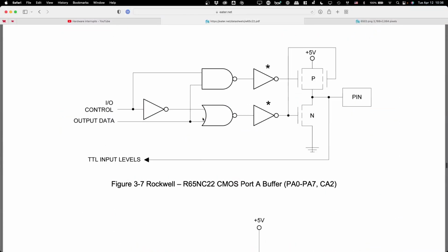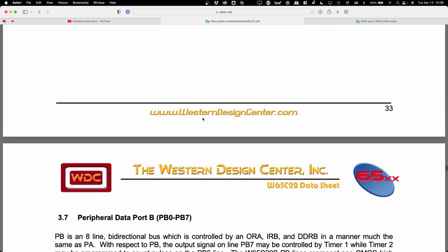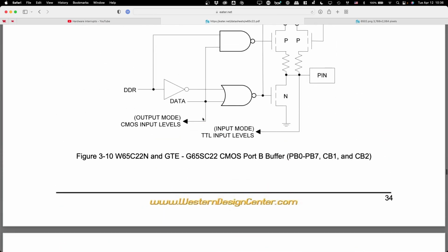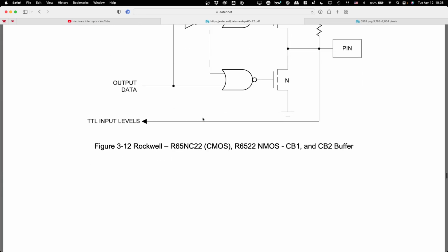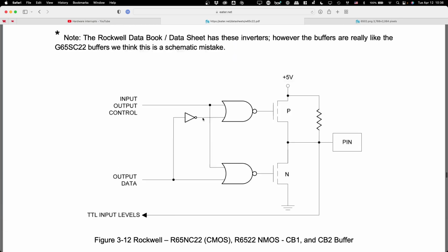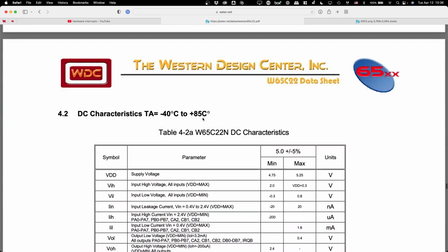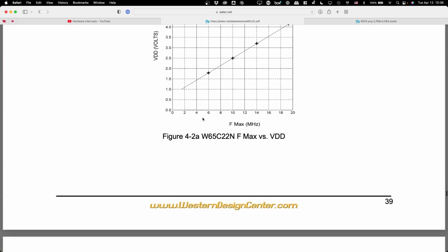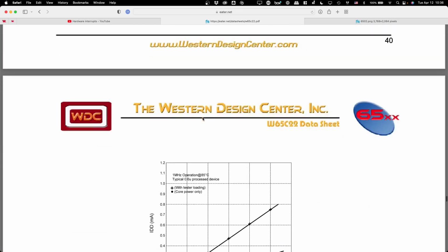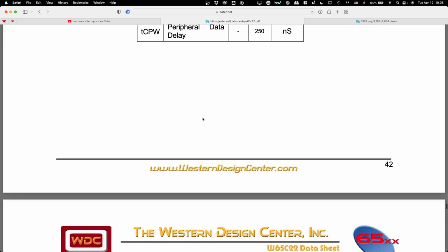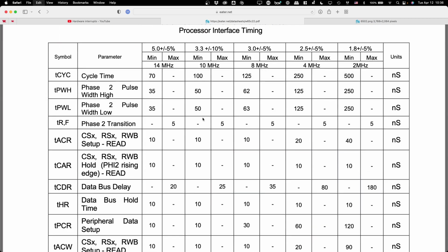Let's see, where does it have the bit about? You can't take 5 diodes, put them all pointing out of the same line. Nope, because what that is called is wire ORing, and you can't do that. You have to do logical ORing. Because the data sheet says not to.